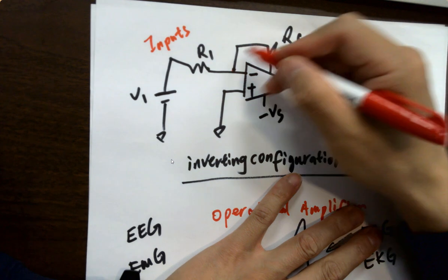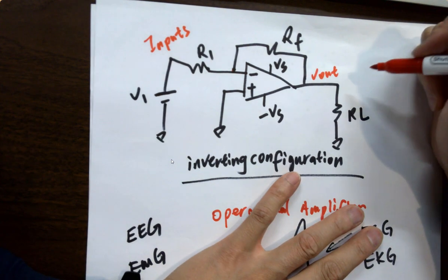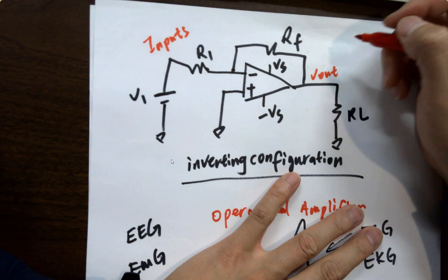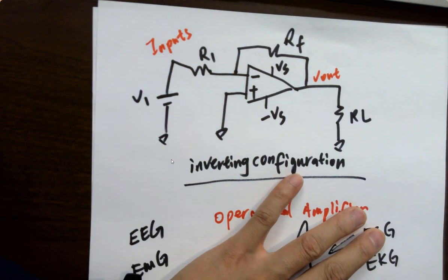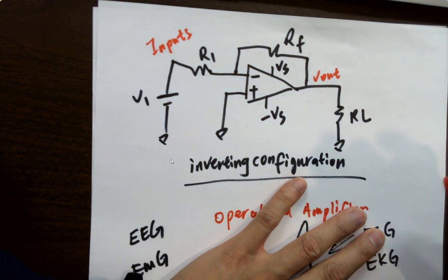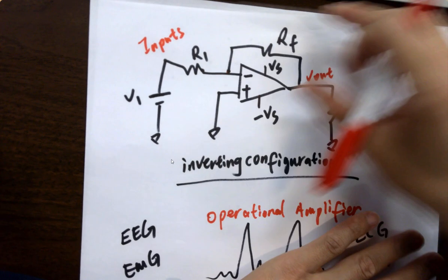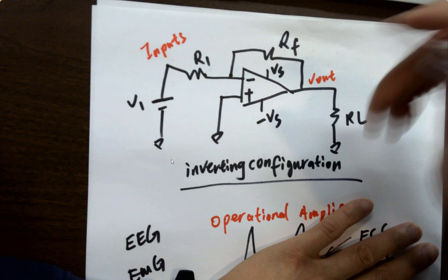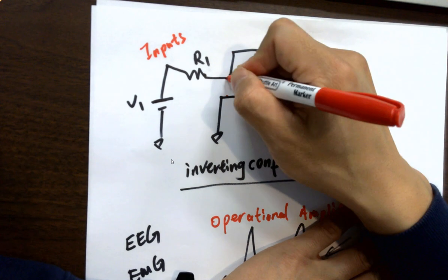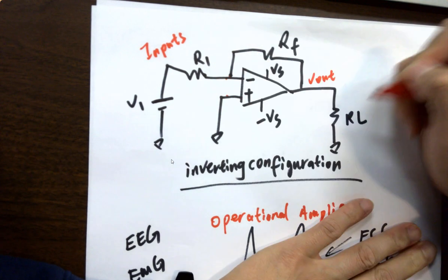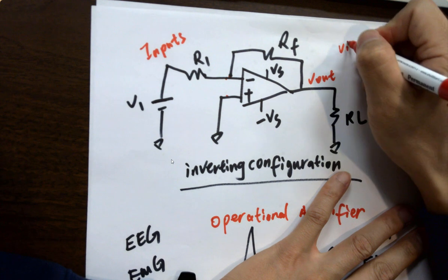All right, if there's a feedback, you have to remember that within the scope of this class, we're not dealing with all the little bias. Bias is a voltage difference, okay? So we just disregard that. So you have to know the voltage at these 2 points are equal. It's called virtual short.